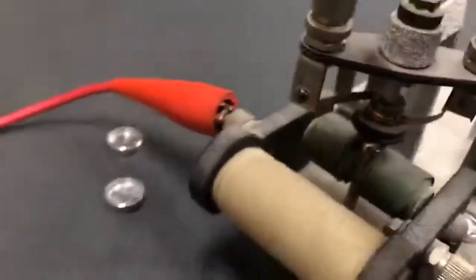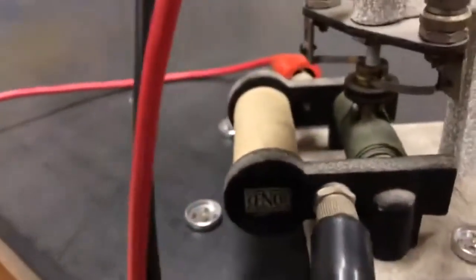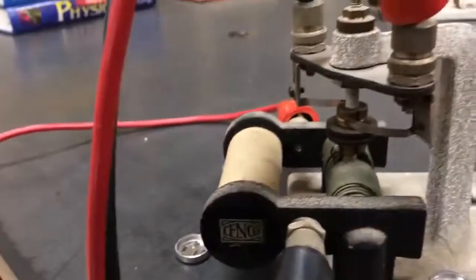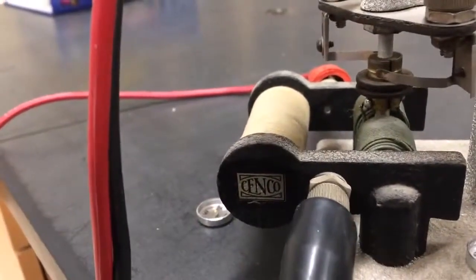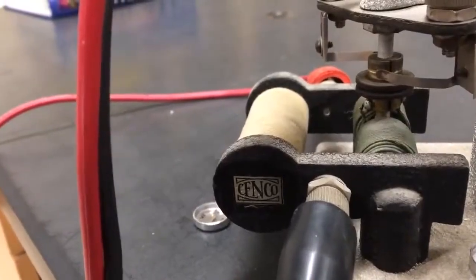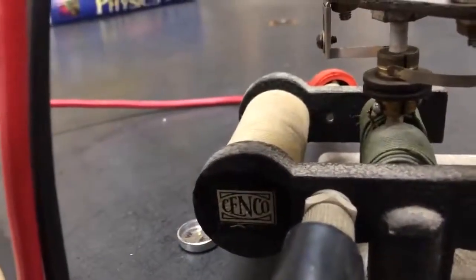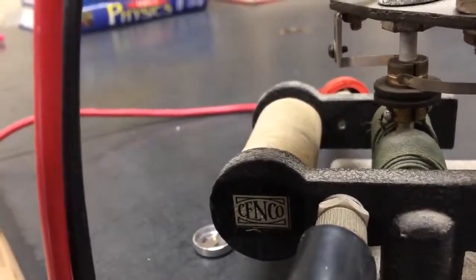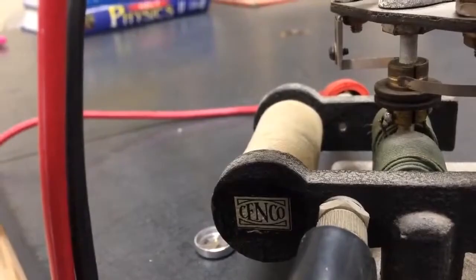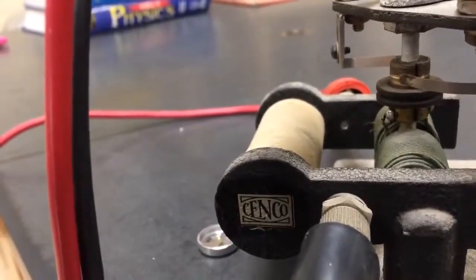And these things that are touching the spinning part, these brushes, they're what are actually hooked up to the power. And they alternately touch one side of this metal spinning jacket or the other. And what that means is it's constantly switching back and forth whether positive or negative is touching each side of the jacket.